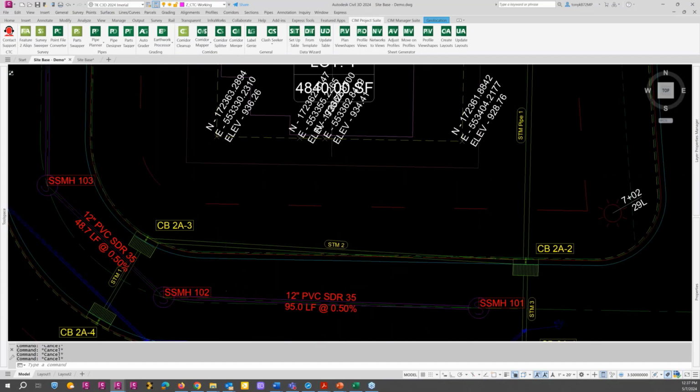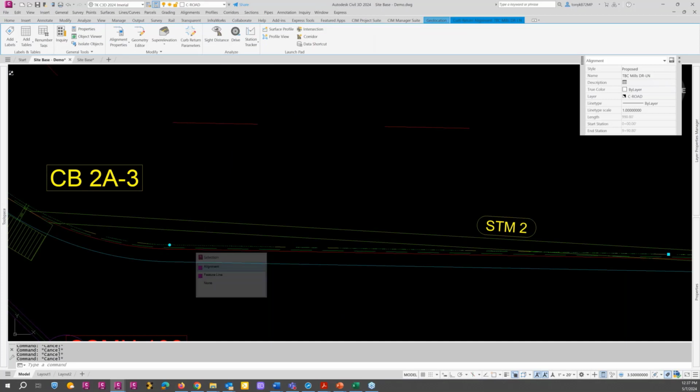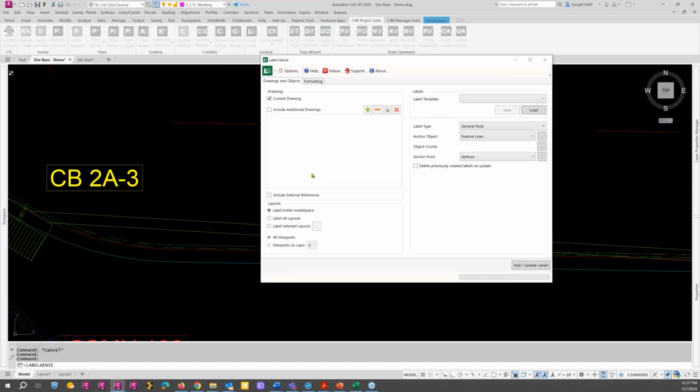Looks like we've got a little bit of time here. You've seen how this works. So let's do that one more. I'll do that with Label Genie again. So I'm going to come back here. I'm going to do this right from scratch this time to show you guys, again, how you would do that. So I'm going to do the same thing, alignment, station, offsets, and I'm going to leave it at feature lines.